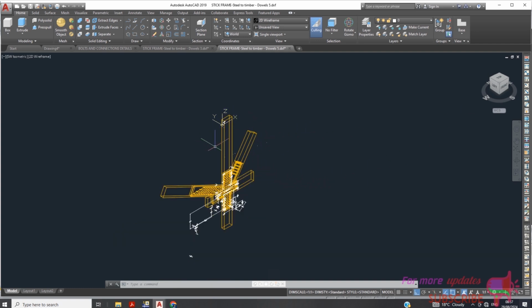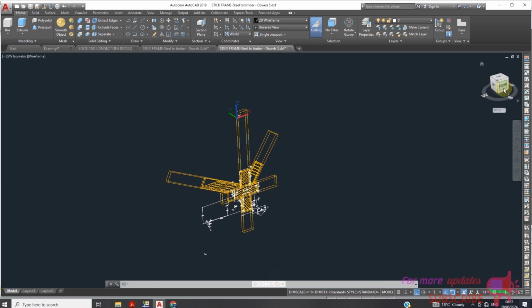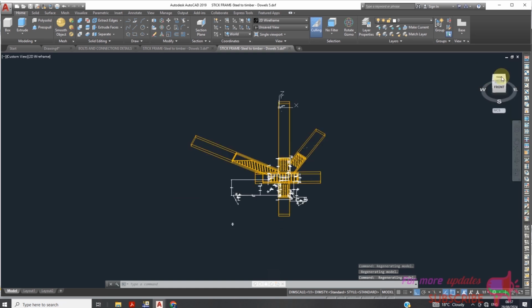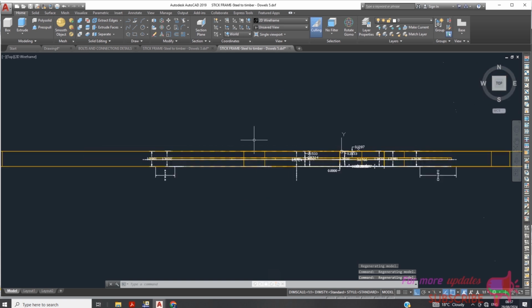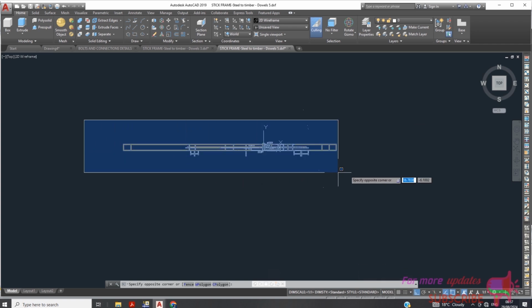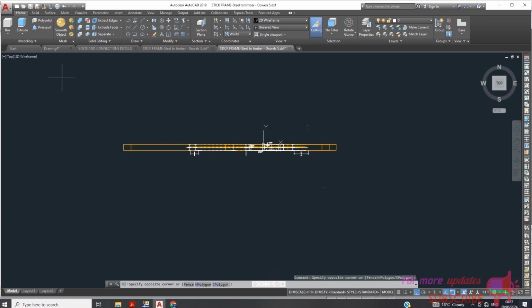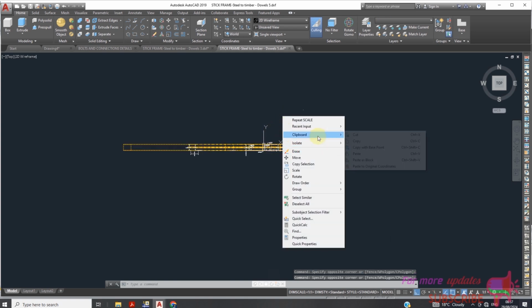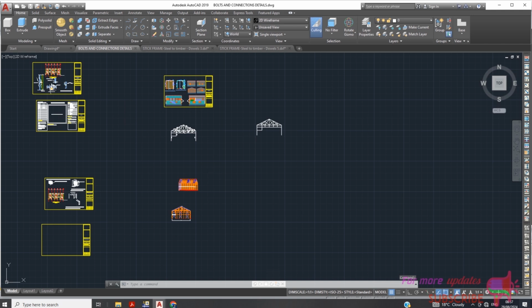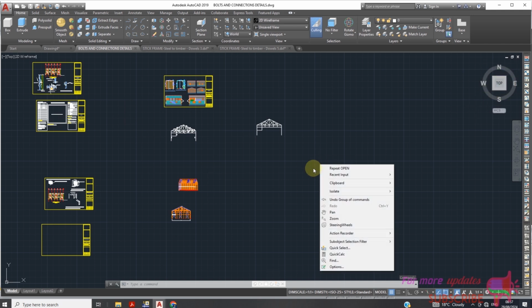So this object is currently aligned to the front view. We might want to realign it to the top, so that if, for example, I copy these into another drawing, into a new drawing, I will not be able to paste it properly. It will appear like this. If I paste it here where I need it, this one is aligned to the top, it will appear like that.